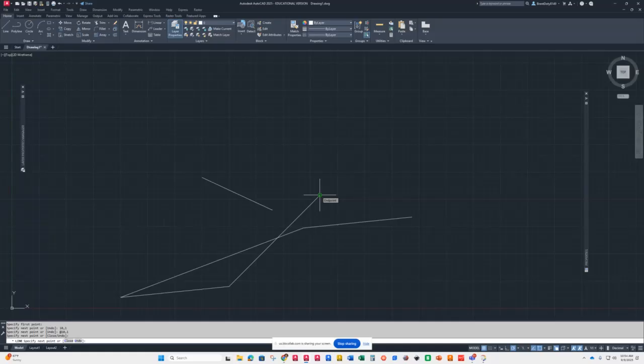Well, when you have dynamic turned on, so let's turn that, and I hit enter to finish out my line command, okay? So then if I were to turn dynamic back on, which is where it should be, and I do line, and I pick here, and I type in 10, 1, it's relative, right?